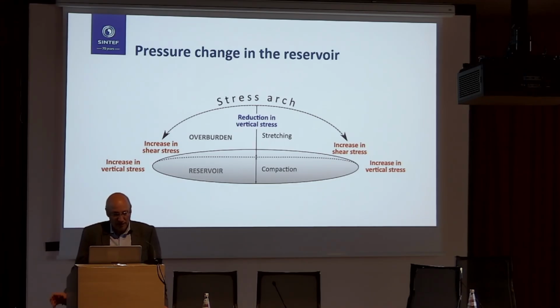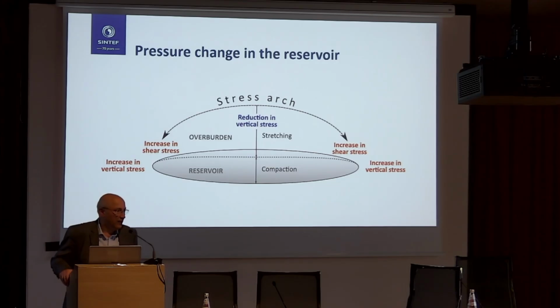But if we look at the flanks of the reservoir, we actually have an increase in the vertical stress there. This is due to some arching effect, a lot like when you drill a borehole, you redistribute the stresses. And in terms of the overburden, you would probably have a change or an increase in the shear stresses.